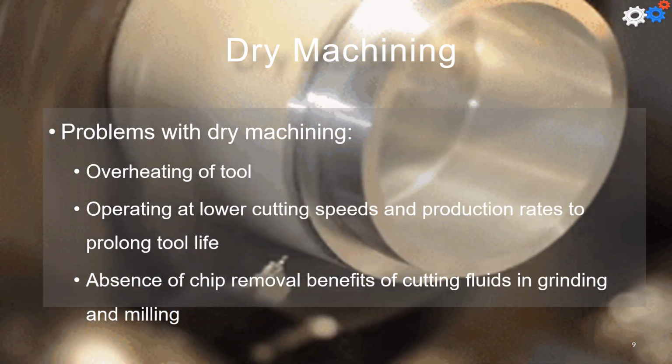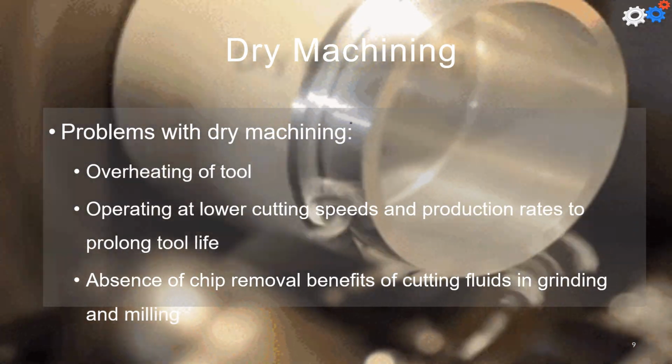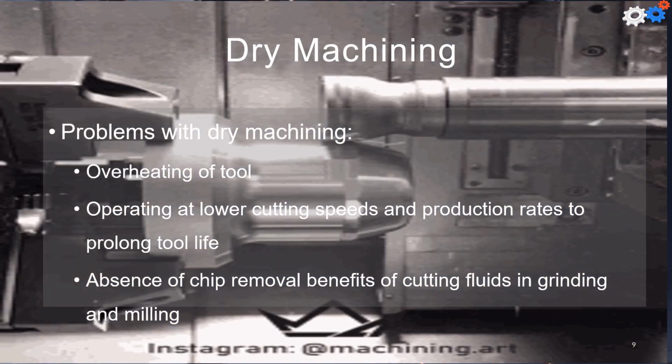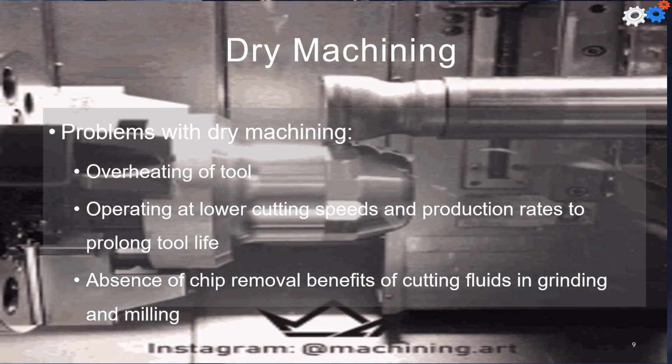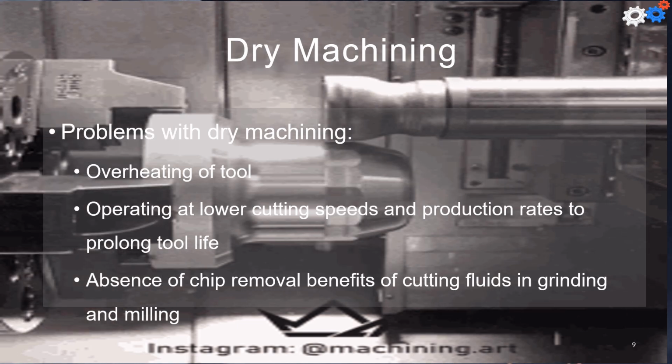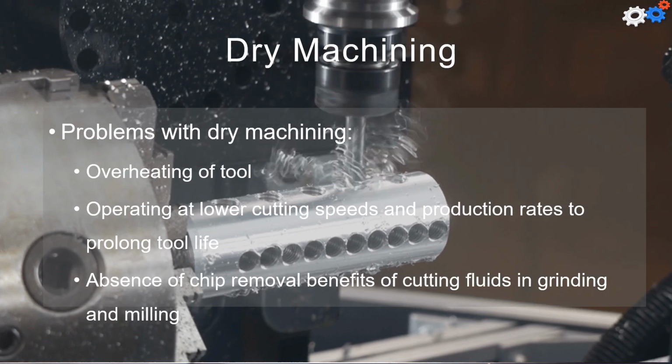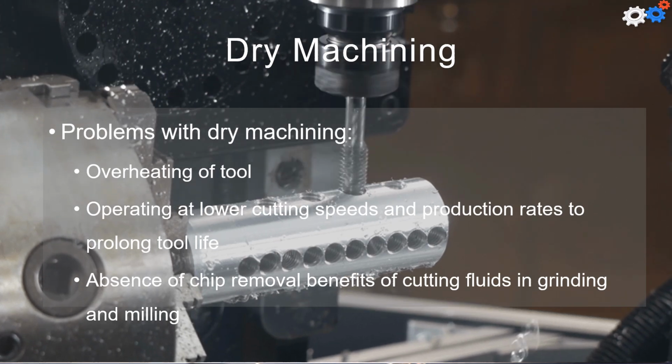But there are problems with dry machining, including the overheating of the tool, operating at lower cutting speeds and production rates to prolong the tool life, and the absence of the chip removal benefits of the cutting fluids in grinding and milling.